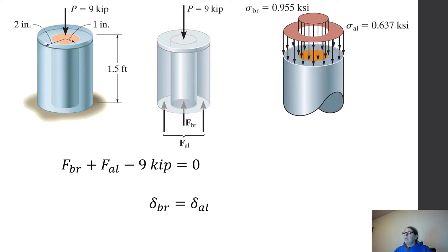Then I can go back, get that internal force for the aluminum and the brass, and ask, what's the stress acting on both of them? Because I know their cross-sectional area, I have to make sure it hasn't yielded, right? What if it yields and we have a compound system like this? I will show you, but not today. It's super, super cool.